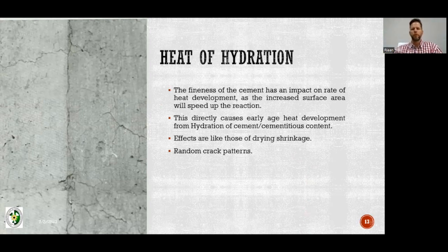What can you do? So they were considering sealing up the crack or cracks, the other ones that they could find, but that doesn't help. Your whole base has now been split right through the middle. So there's no point. That crack goes in, who knows how far. You'll have to follow it with a core drill and establish how far the damage is. How do you seal up that whole crack? You need something that is sustainable and that's safe.